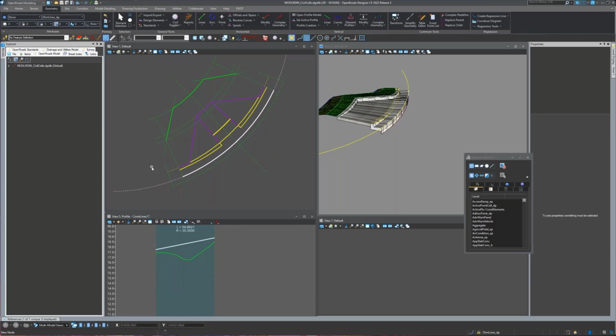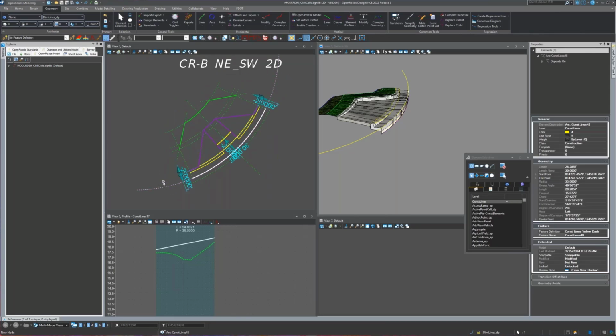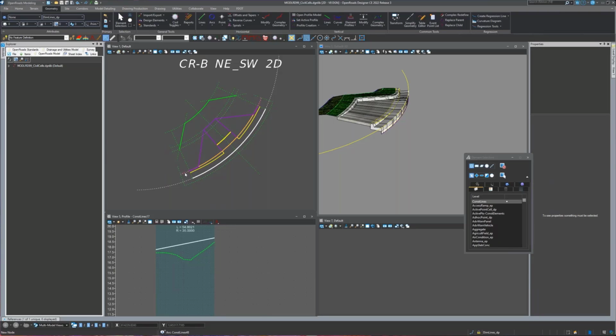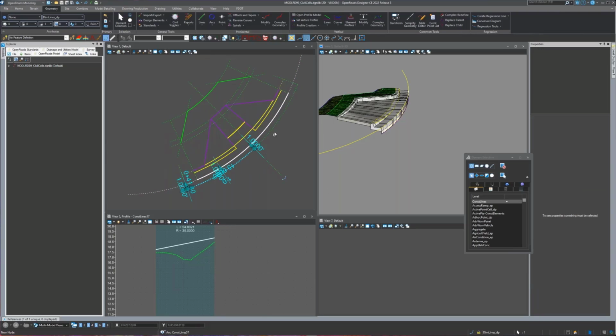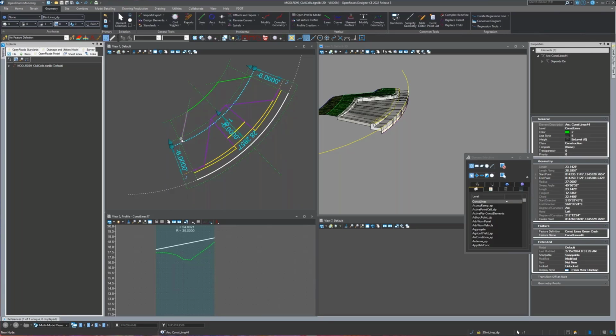If I offset this the entire way, this line would go the entire length of the curb return, and I don't necessarily want that to happen. So that's why this rule is bounded by this 15-foot width on either side. When I offset this, it's 6 feet, so that's your regular sidewalk width from the curb. Then we've got another one that's 7 feet, so that's my ramp. And then another one here that's 4 feet, so that I've got the 4-foot landing that goes around the ramp.